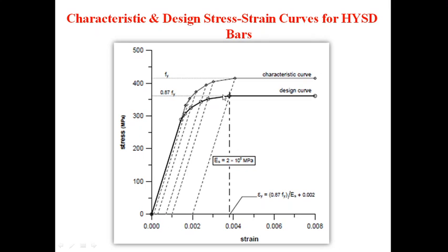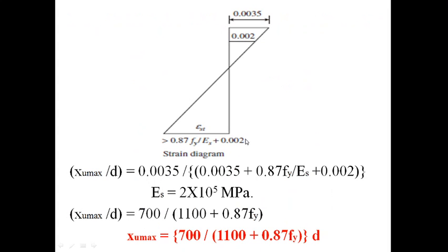That is the yield point they assume, because it is difficult to locate the yield point. So they assume that 0.002 is a strain in the body of the steel. Already that much strain is in the body of the steel. Sometimes we call it a permanent set. And that is the reason why 0.002 appears here. Now let us see what happens next. Now here this is the neutral axis.